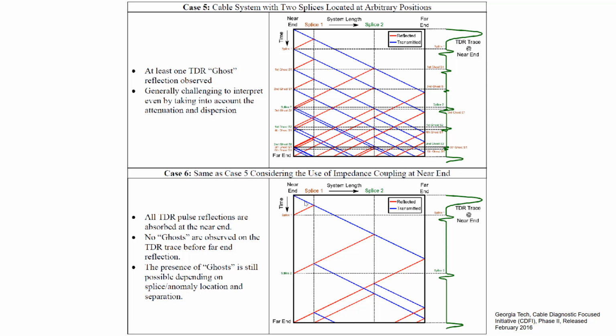But you can see here, this is the first reflection, this is the second reflection, and this is the third reflection due to reaching the far end. These multiple reflections are occurring, but they are not re-entering. So if we use proper coupling at the input, then you can avoid these kinds of ghost reflections. But if the matching is not perfect, because cable impedance may be different for different cases, obviously you are going to end up with several reflections like this.